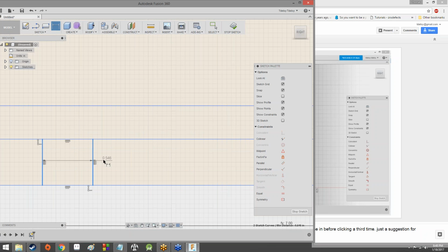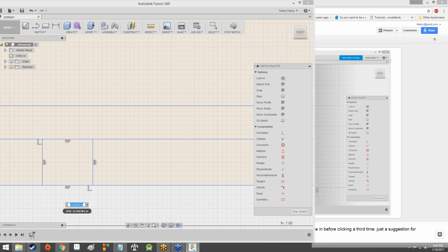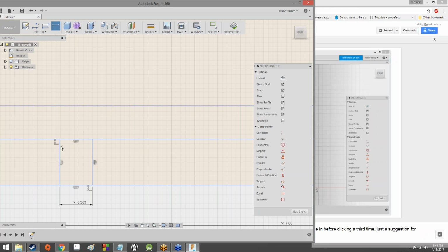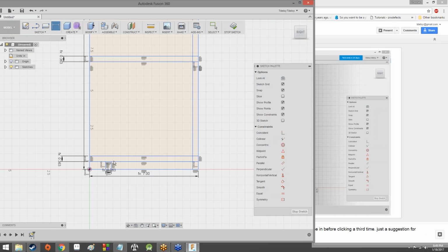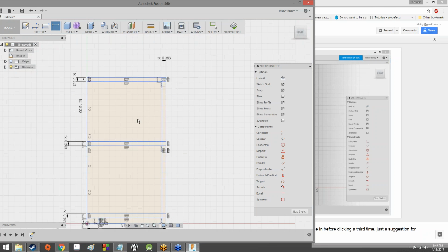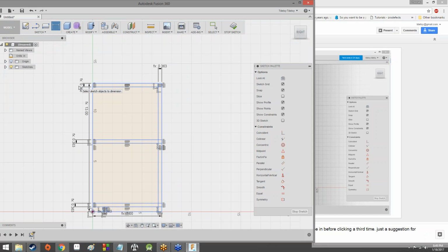And notice down here, remember how I said that this was a vertical rectangle, even though it's kind of hard to tell because it looks largely like a square. I clicked on the left and right walls and then dimensioned it down this way because I want the thickness of it to change horizontally. So now I've dimensioned all of these rectangles themselves so that they have a thickness of ply.